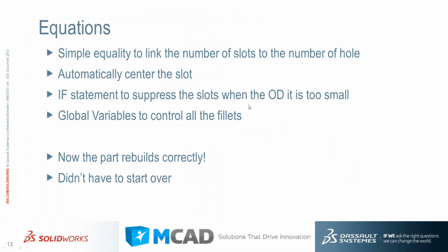So we've got everything linked. The number of slots matched to the number of holes, automatically centering the slot, if statements when we need them, global variable to control the fillets. And the important thing, it rebuilds correctly and we didn't have to start over. That's what I want to emphasize here.